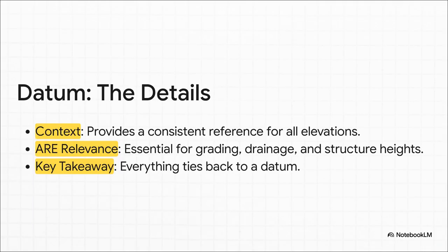And you better believe this is a big deal on the ARE. Every single decision you make about grading, about drainage, even your building's finished floor height, it's all measured relative to that datum. You have to make sure water flows away from your building, and you can't possibly figure that out without a consistent reference for what's up and what's down. So for the exam, burn this into your brain. Everything ties back to a datum.